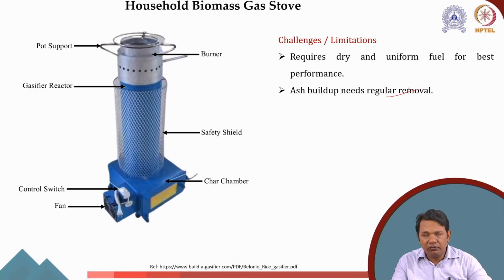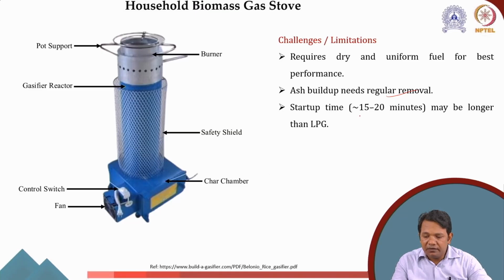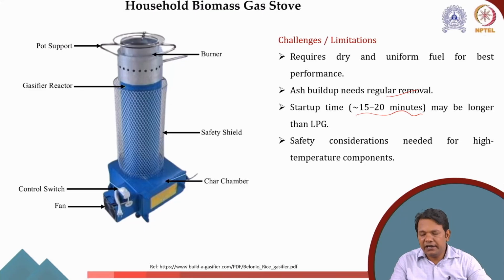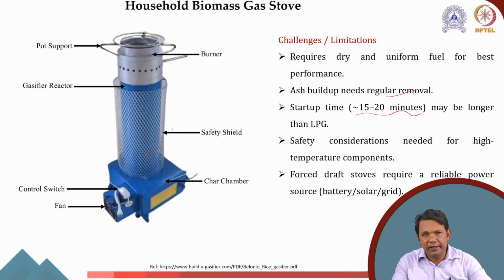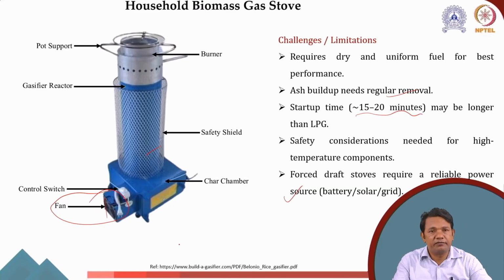Ash buildup needs regular removal, otherwise the whole gasifier chamber will get filled gradually over time. The startup time is 15 to 20 minutes, which is longer than LPG, which burns in seconds. Okay. Safety consideration is needed for high temperature components, like we have put a shield here, some people don't put the shield. And the forced draft stoves require a reliable power source, particularly the image that you see here. This definitely requires a power source. Otherwise, we will have to remove the fan and we will have to use a natural draft.